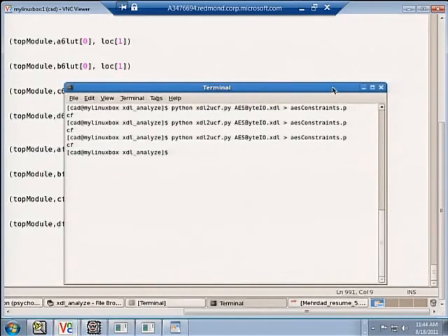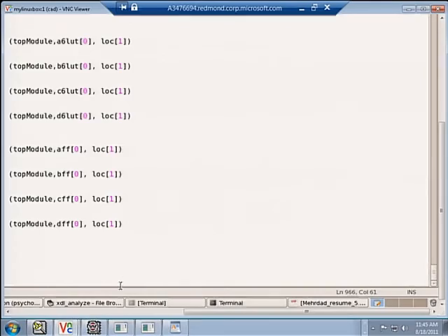So the other tool is the XDL to PCF. After you do your design, at the end of the whole process, Xilinx spits out a file in the format XDL, which stands for Xilinx Description Language. It's a closed language, but it's easy to understand. It has a very simple syntax, and it's the netlist of the FPGA: how things are connected and how things are placed. For example, I'm going to open up one XDL file here and show it to you.